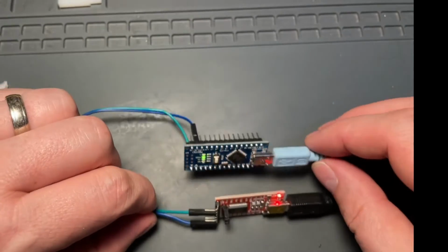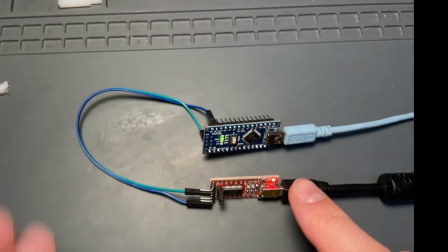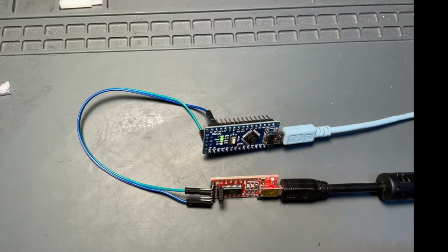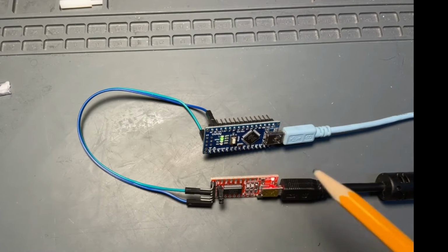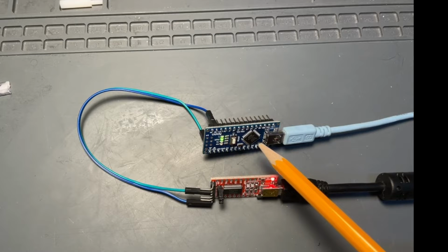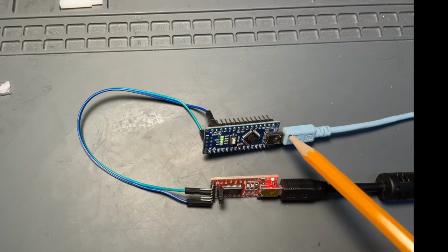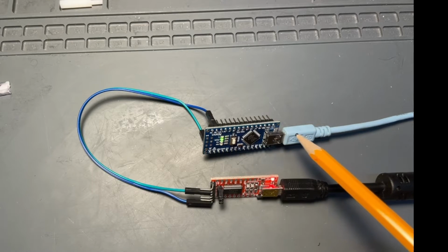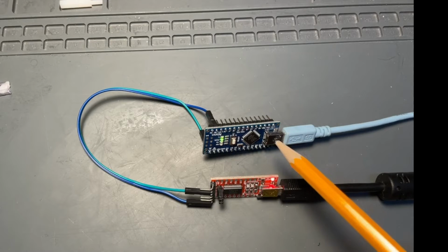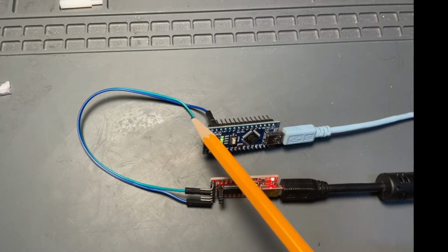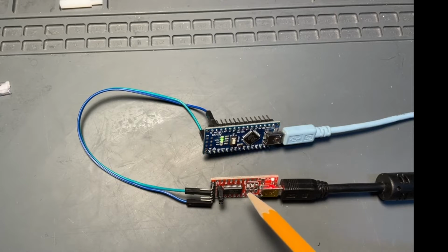With this plugged in, we now have two sources of the same information. The ATmega chip is sending this transmission towards this blue USB port with its built-in CH340 converter, but we are also taking the same transmit signal onto this second converter. I'm doing all this just to prove that it's that CH340 that is broken.